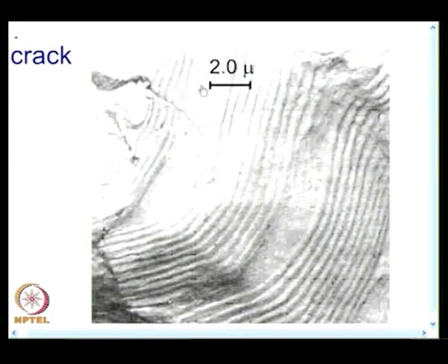So, the specimen carries this signature, and in fact, you could find out what kind of loading it was. There may be an overload here, repeated overload. So, you find that there is a shift here, there is a very long crack growth. All that kind of analysis metallurgists do.